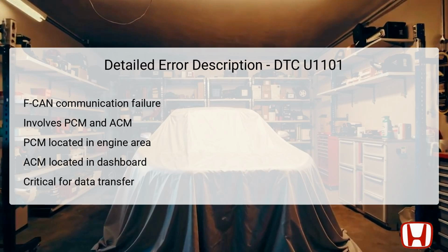system attributes. An effective communication link is essential for systems to work cohesively, and a malfunction may cause components to operate in isolation. This may lead to symptoms affecting the vehicle's operability and driver experience. To accurately diagnose the issue, identifying where the communication breakdown is occurring is essential. Verifying connections, checking wiring, and confirming module functionality become crucial steps in this process.